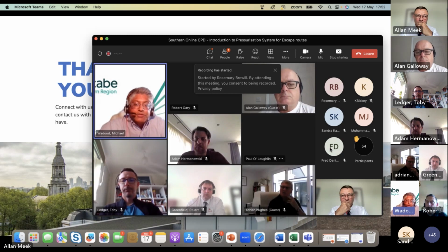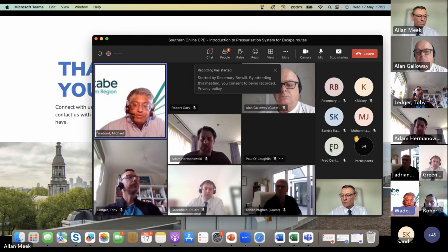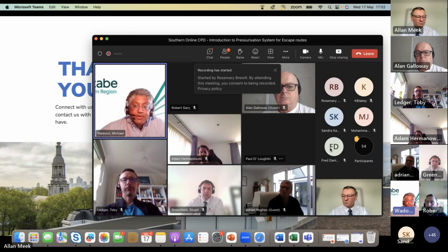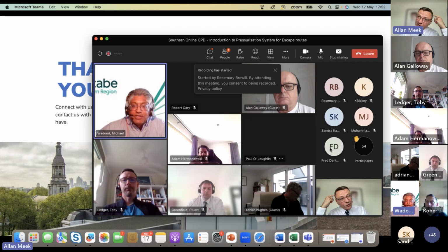He goes on to say, obviously aware of the approved document B consultation looking at removing single stairs as an option above 30 meters, there's potentially 2 pressurized stairs lobbies would then be required, which is a lot of floor space being used and a large number of shafts. Can stairs potentially share a pressurized system? Would this be practical? So that's actually in the chat if you want to have a look, because he was kind enough to write an essay.